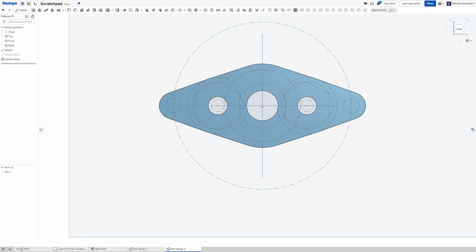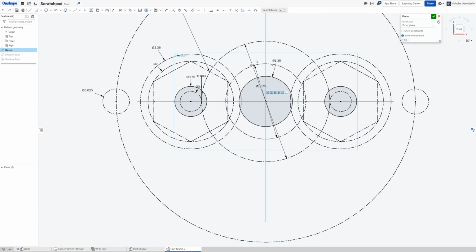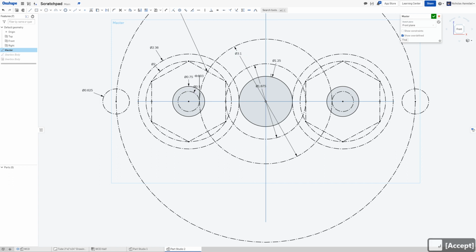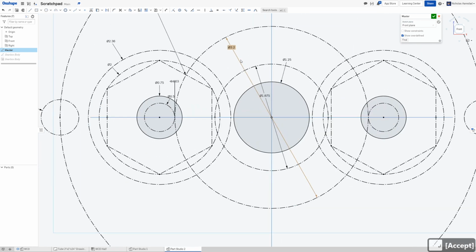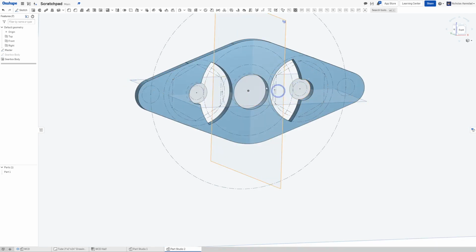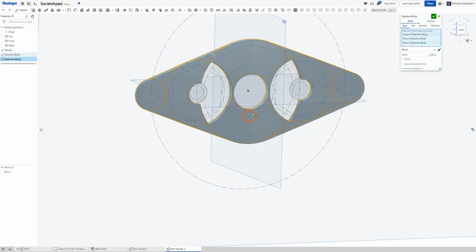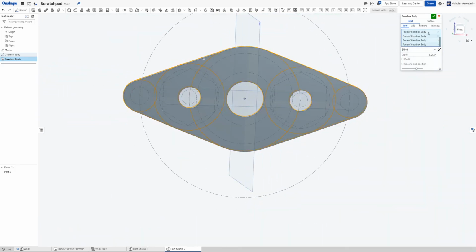This gear spacing also looks like it's going to leave this interfering with a bearing flange out here, which we could do a few different ways, but for simplicity of assembly, I'm going to flip that around. So maybe I want this to be, instead of a 60-tooth gear, let's flip that up to 62, maybe 64. Like anything in CAD, there's different ways to go with this, but this is one way. So now you notice that messed up that second sketch a little bit. That's fine. You just go back and we select these things, and that'll fix it.